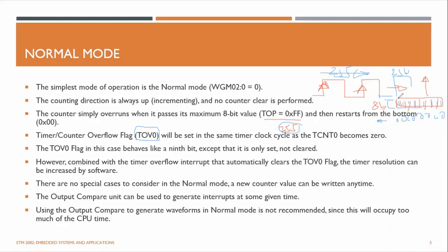So that's how you can, if you want to count more than 255, make an interrupt and push that value to another variable and count it as a 1. Likewise, you can use this overflow flag for different applications, but make sure you understand the following.